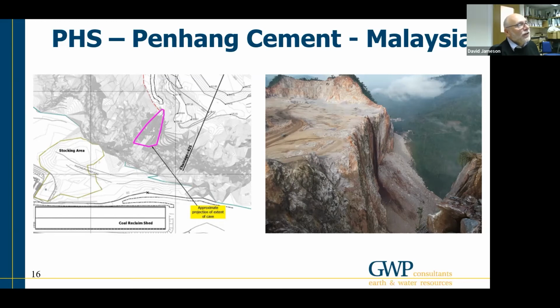However, you can see at the far end on the northern side of this particular hillside, there's some slopes that have been left in place. And the reason for that is there's a lot of infrastructure just on the other side, which would be at risk if blocks fall from that, and the coal sheds and some of the processing areas at the bottom of the slope. Just for scale there, you can see some pretty precarious end tipping from the edge of that slope, with the guy reversing up to the edge without any particular edge protection and tipping materials directly over the face. And that slope there is about 300 meters high.